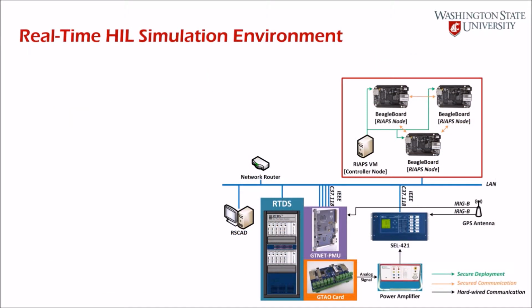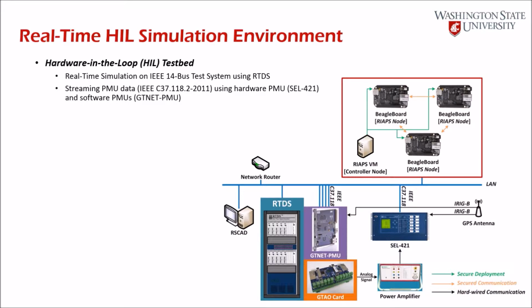To simulate the wind curtailment RAS application, we built a hardware-in-the-loop simulation testbed. This testbed runs the real-time simulation of the IEEE 14 bus test system using RTDS, the real-time digital simulator. Our testbed is also developed to stream PMU real-time data using a hardware PMU, such as the SEL-421, and a software PMU, like the GTNET PMU card. And the testbed is designed to execute RAS control commands under TCP/IP socket protocols.